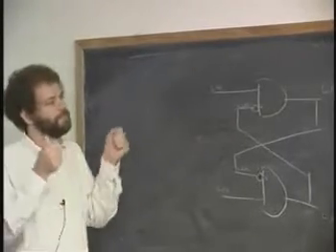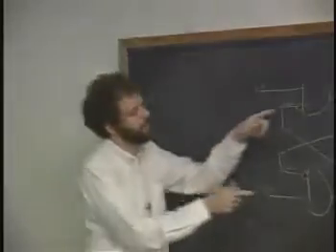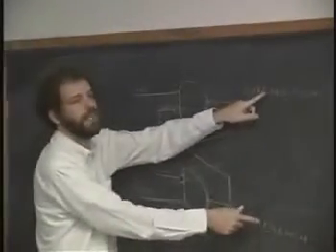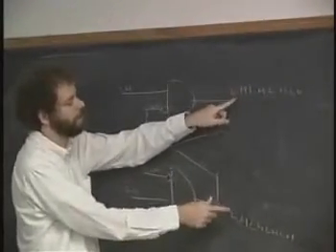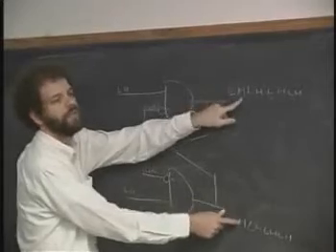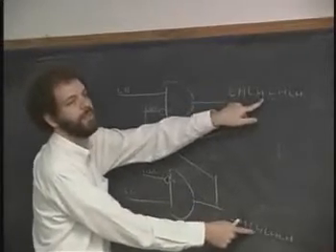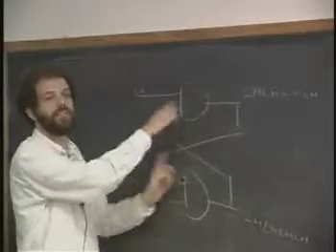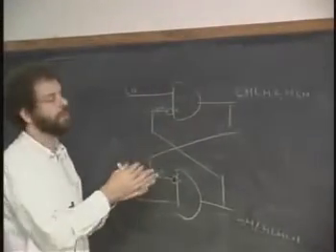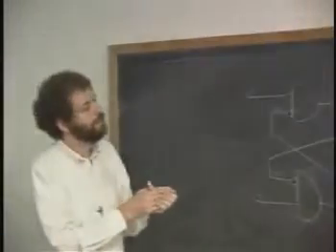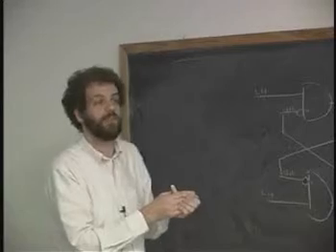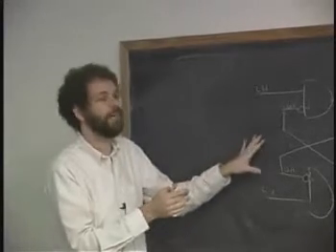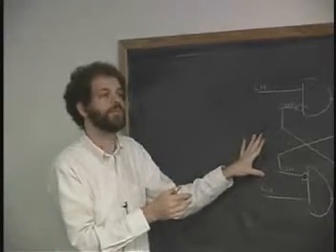They sit there and they keep... Now notice it's not really making up its mind in either of the cases. It keeps flipping back and forth between no one won and everybody won, and no one won and everybody won. And the ones and the zeros are chasing each other around in this loop, okay, which is just a weird thing, but it can happen. Okay? And circuits like this, in fact, if you hook an oscilloscope up to them, can oscillate.